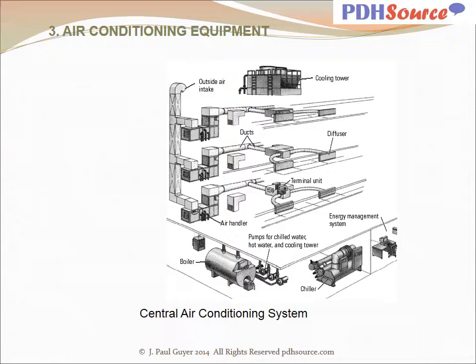So there's the compressor, there's a condenser coil, there's an expansion valve, there's an evaporator coil, but instead of air being blown through the evaporator coil and being cooled, it is water that is pumped through. And so what comes out of the chiller is chilled water. It's cold, and there are chilled water pumps that pump that water.